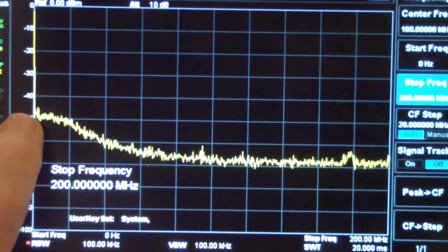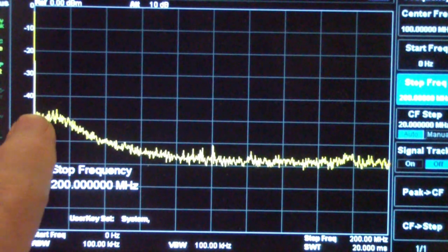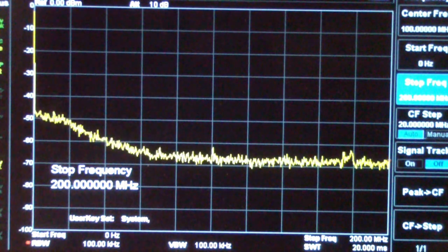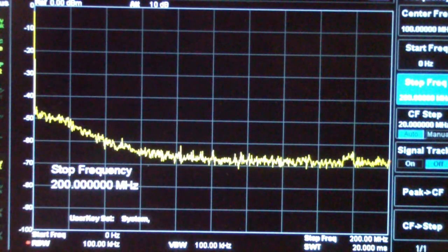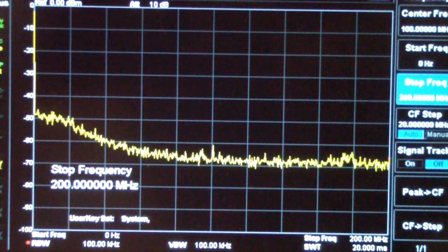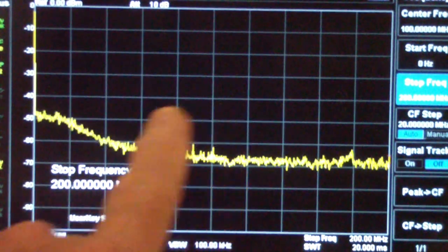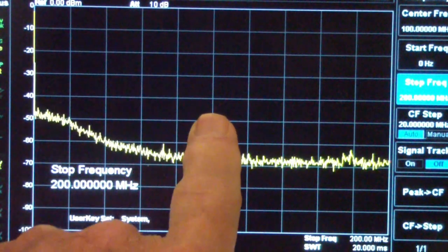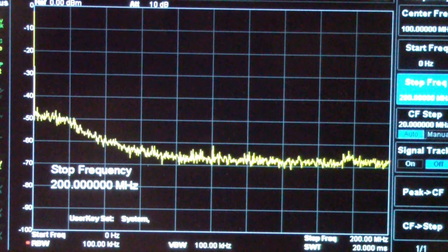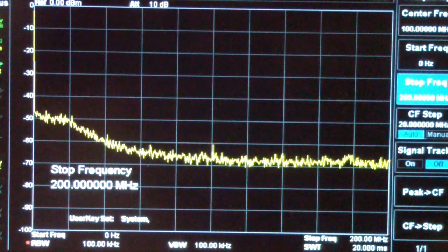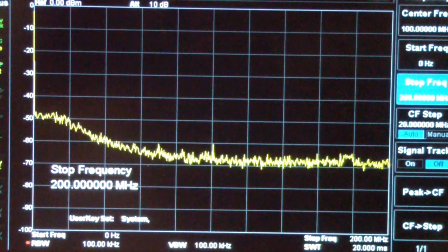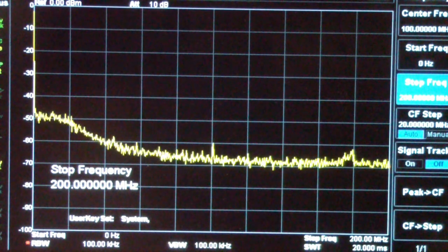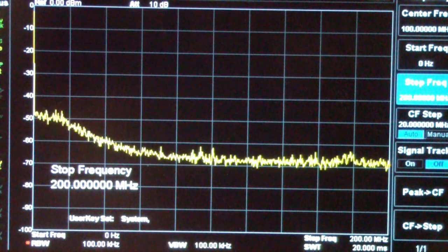That is, what we would like is something that will at least go out past the 150 megahertz range so that it's useful out to, say, 2 meters for an amateur radio operator. The wider the better, because a nice flat noise source going out to 400 or 500 megahertz would be ideal. But I will tell you that the noise source that I ordered from Ukraine claims to go out to several gigahertz. So we'll see when it gets here what it actually does.